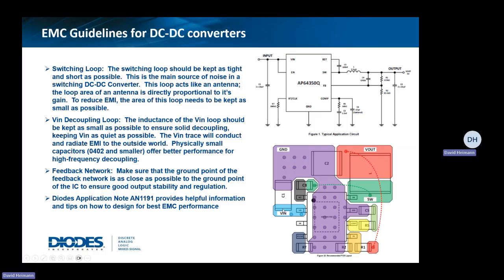This part could be a 0402, 0603, 0805, whatever size it would need to be. But 0402 is okay, while 0201s and even smaller size capacitors will give you better high frequency performance at your VIN decoupling.